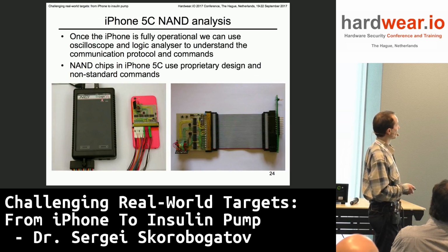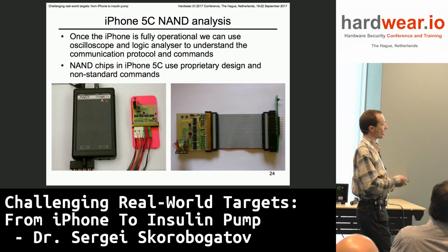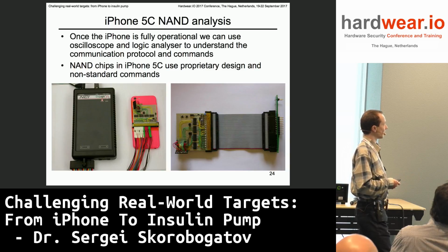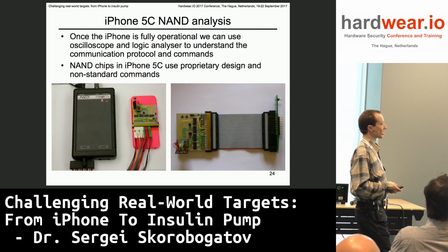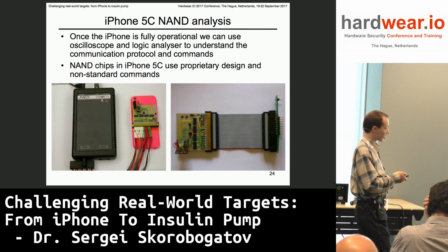So once I got the iPhone back to operation, I hooked up the logic analyzer and figured out what communication protocol they use, because the NAND chips inside the iPhone are non-standard. They don't comply with the standard specification for NAND chips, and they use proprietary commands. So you have to figure out all the commands and how to write, erase, and read the flash.